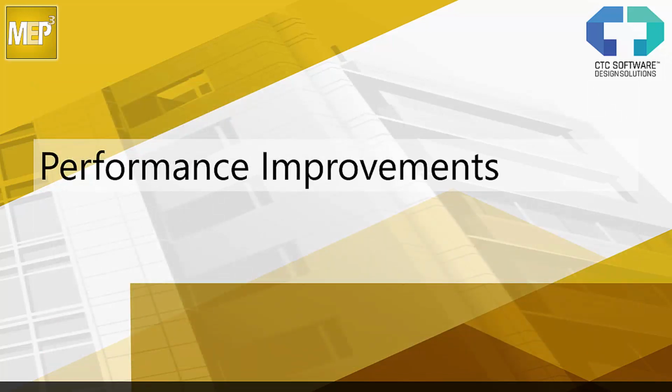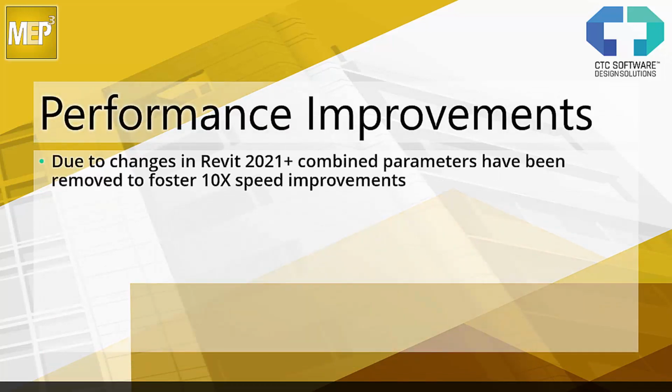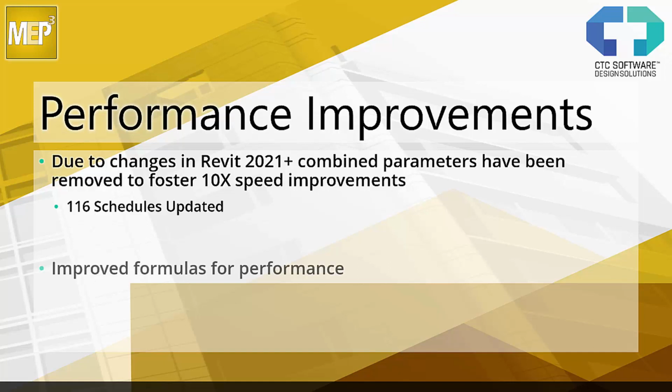First off, performance improvements. These are really important. There were some changes in Revit 2021 and newer versions where combined parameters weren't able to properly work within the MEP Productivity Pack. It's a Revit change, out of our control, but what we've done is modify how we are leveraging these combined parameters. In fact, we aren't using combined parameters, and it makes the model 10x or more faster when working in Revit 2021 Plus. This affected about 116 schedules that were in the original pack, so all of those have been updated in this .1 version. We've also improved formulas for overall performance within the families.